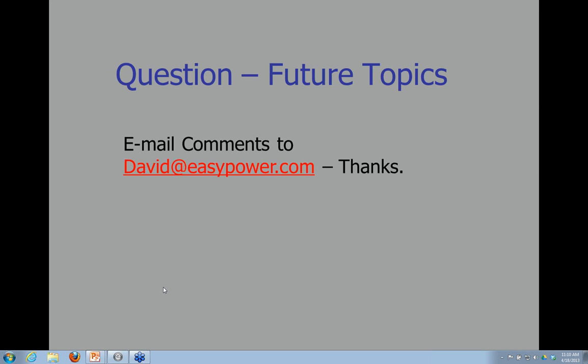And then, going along with that, the current in the equipment duty report would correspond directly one-to-one to the device you're using. Exactly. So it's going to be specific to that breaker. It's a more accurate analysis. It's especially important if you have generators on your system and that kind of thing. Yes, which I usually do. Does that answer your question? Yes. Okay. Thank you. Great.